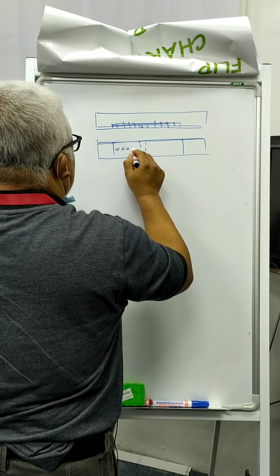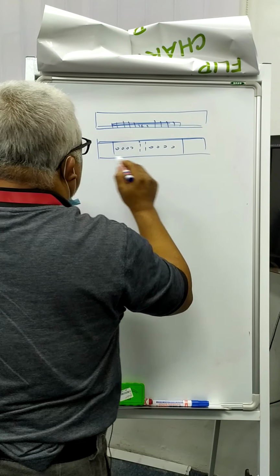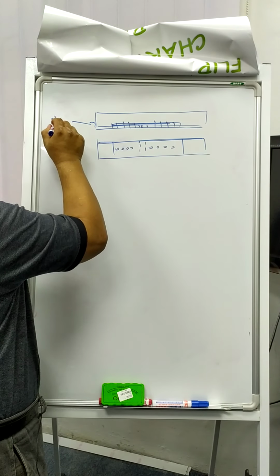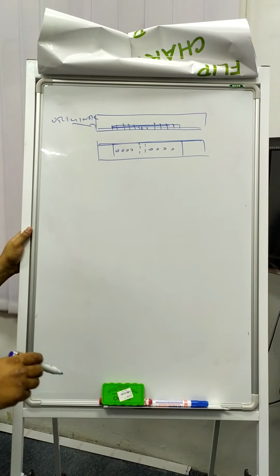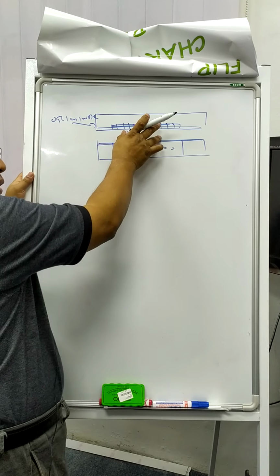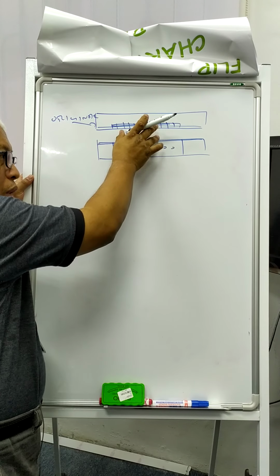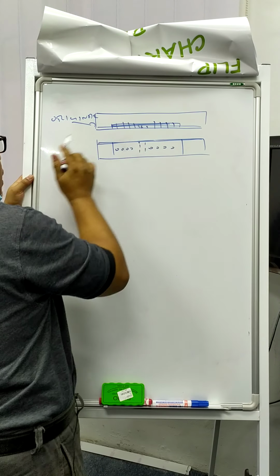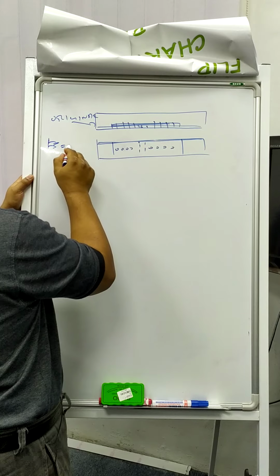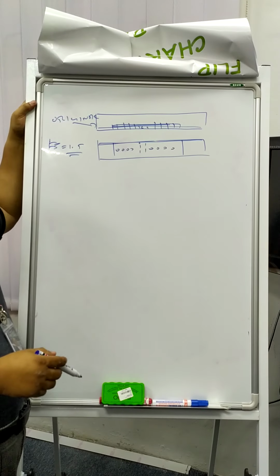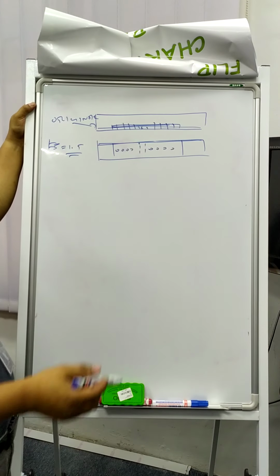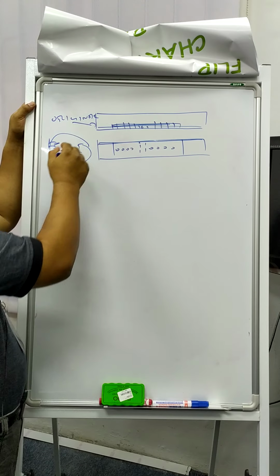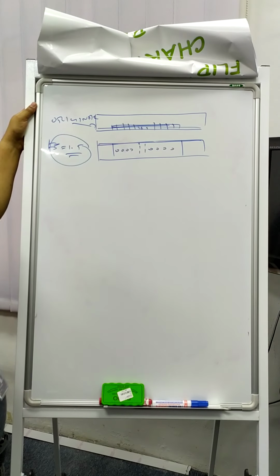This is the original aircraft part. Now you're repairing it. It is damaged and needs to be repaired. Why? Because if you damage a part, the factor of safety is no longer 1.5. That's for sure, so the aircraft is no longer as per the design requirement. You have to repair to be able to maintain the factor of safety 1.5.